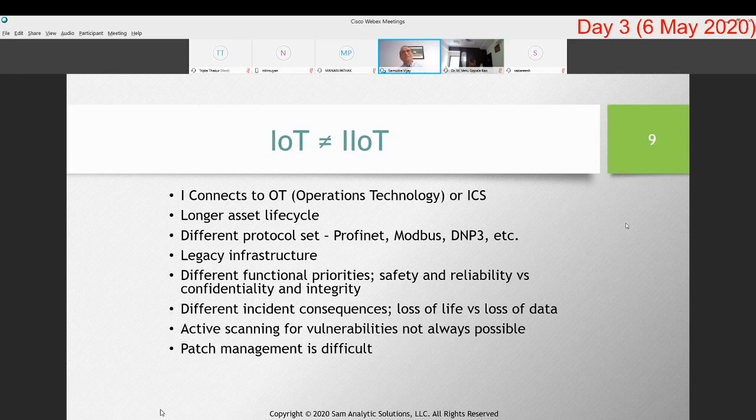Whereas if this was an industrial control system controlling 24/7 critical production infrastructure, you cannot just initiate a firmware update in the middle of the production cycle. It could potentially cause millions of dollars of loss or a complete batch being ruined because of the restart of the device. So patch management is much more difficult, and that's why security holes can potentially remain unplugged in industrial devices for a long time.